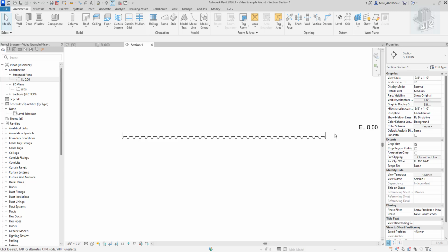Where I've used offsets is if I had say a 4 foot deep sump in here and I wanted a floor for the sump and then 4 walls, I will use negative offsets. So if this floor ever gets higher or lower, then the floor is always going to be whatever your negative offset is, 4 feet. So you got to think about what you're trying to achieve.